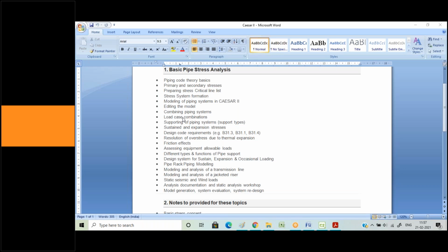So now when you're placing it below the line, what you are basically assuming is that the line is not in operation, so obviously it should act like a dead support. So basically that particular spring in the sustained case, because the line obviously would be having the insulation and everything, must behave like a rigid support in your sustained case.